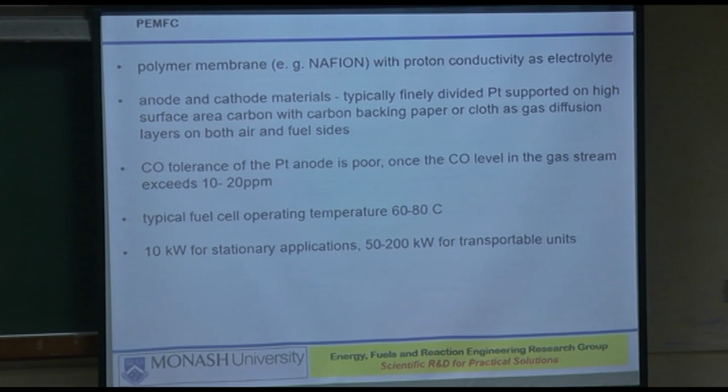If you buy a gas chromatograph from a reputable manufacturer, then they will ask you to install a Nafion filter at the inlet to the gas chromatograph in order to clean up a lot of gases, moisture, and particles. So that's Nafion. Nafion is cheap, readily available. You can make your own Nafion filter if you want. But anyway, that's used, and it's highly proton conducting. So that's an ideal material.